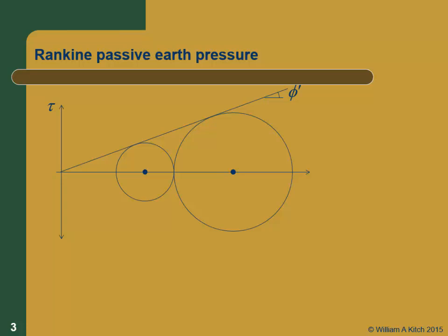And remember when we were looking at that ratio, at that little displacement chart before, the difference between the passive K and the active K was much bigger. Notice that your passive horizontal earth pressure is much bigger. The difference between that and your vertical stress is much bigger than on the active side. In other words, the passive circle is way bigger than the active circle, and it took more displacement to get there. If you're changing stresses more, it's got to take more strain to get to a bigger change in stress. So this is consistent with our observations about displacements to reach the active and passive pressure and the magnitude of the active and passive pressure.